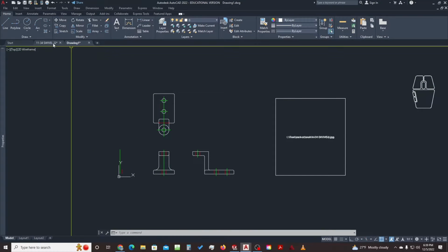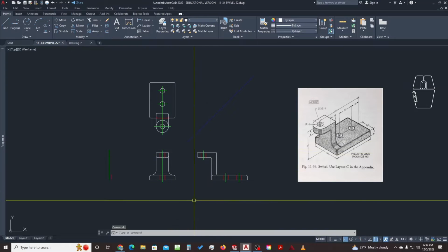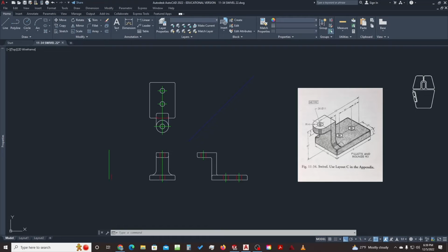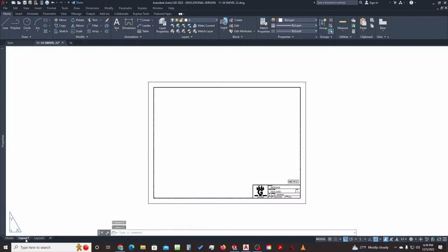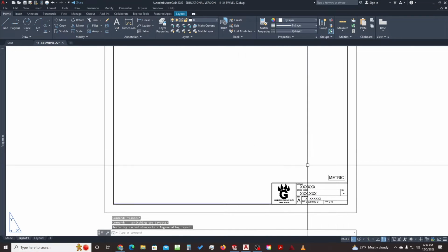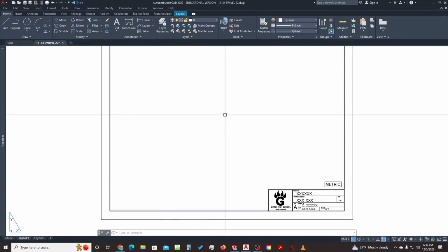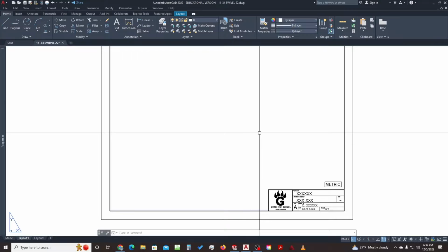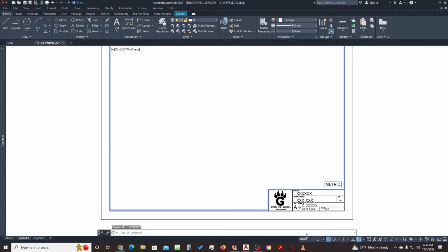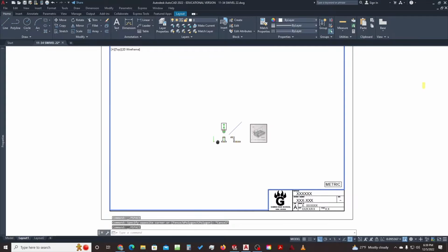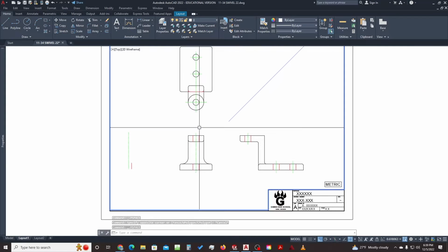Okay, I'm going to jump back to the other drawing. All right, so we're back here in layout 1. Let's add the information for this in a second, but just because I don't like to bounce back and forth between two screens, first we're going to double click in here, and the other option is to select the model or paper. So click the word paper to change it to model, or double click inside. You'll see it'll switch to model that way as well. And zoom out until you find your stuff, then zoom back in on the part.